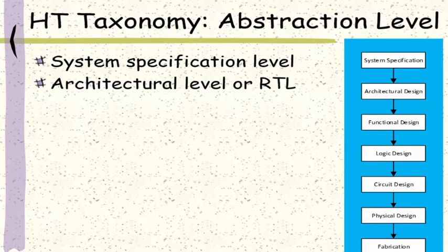A hardware Trojan, as we have shown, is inserted, so the circuit can also compute the square of 10 and 11 correctly. In that way, the system will authenticate attackers with the pairs of 10 and 100 or 11 and 121 as their username and password. This is a hardware Trojan inserted at the functional level, and it is done by adding 10 and 11 as valid inputs to the system.